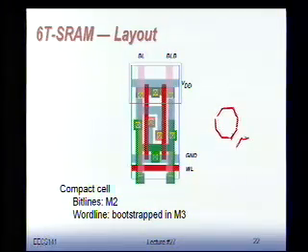Now, this is not something you do on a Sunday evening. It really requires a lot of effort. Designing a good SRAM cell that's really tiny takes a lot of effort. And it's very important, as I said, because 80% of your chip might be SRAM. So saving a little bit here and there has a big impact on the cost of your chip. So this is the job of a SRAM designer. It's really very tiny, trying to compress everything together. And as you can notice, it's 6 transistors, but there's actually quite a bit of contacts in there. Sneaking in those contacts is not easy, because contacts are fairly large, and they kind of almost dominate the area. So a lot of thinking goes into that.